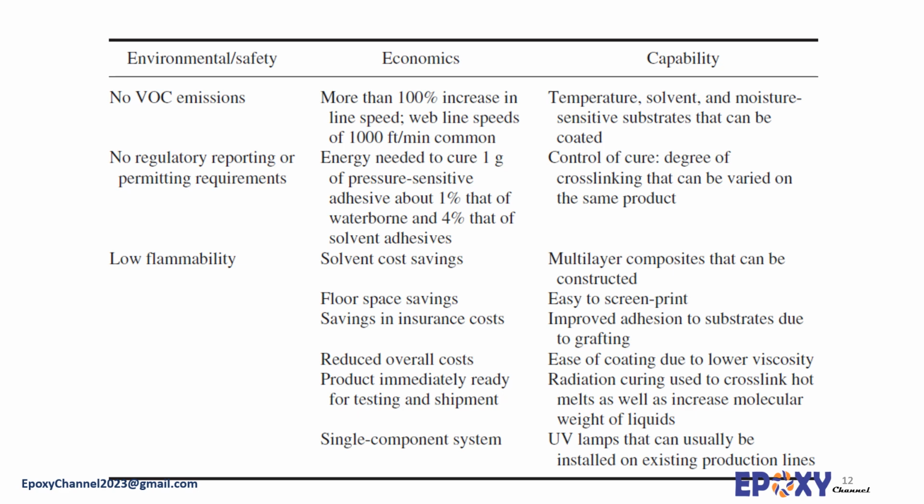The main disadvantage of radiation curing epoxy systems is their relatively high material cost, as these compositions generally have no low-cost components such as solvents, extenders, or fillers. Moreover, in the application of radiation-cured adhesives, to initiate the cure, radiation has to penetrate to the depth of the adhesives, and also at least one substrate must be transparent to the radiation energy. In other coating applications, especially in complex geometries, shadowed areas protected from the radiant energy create problems.